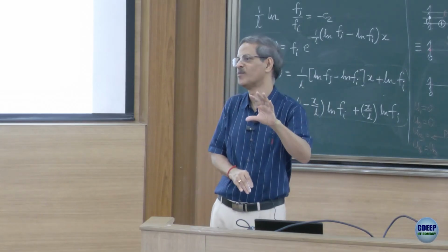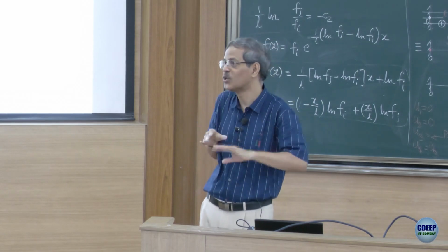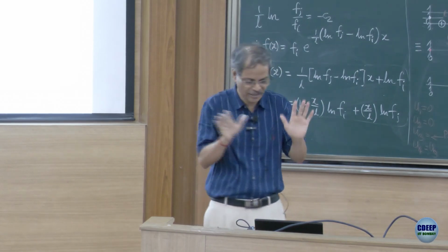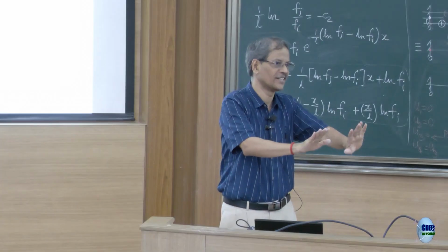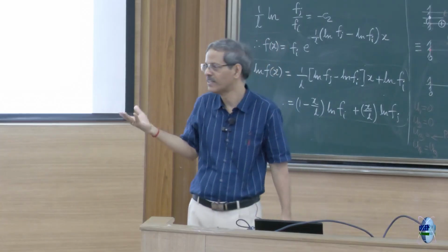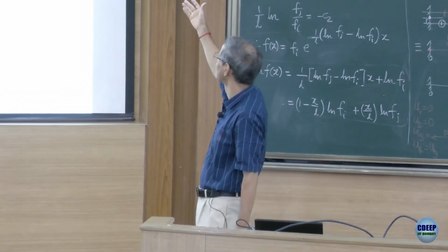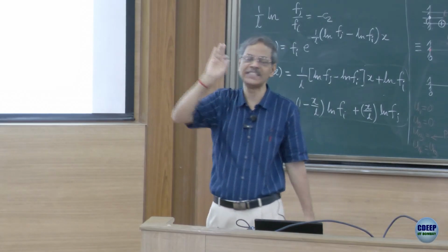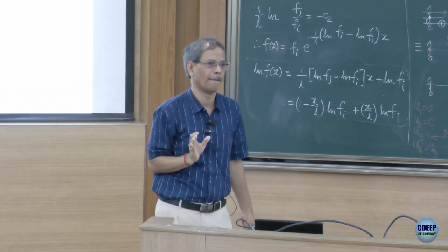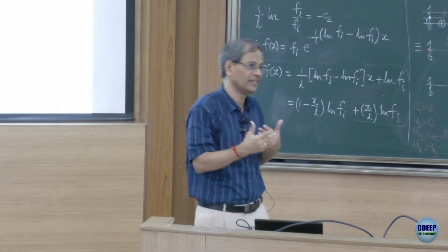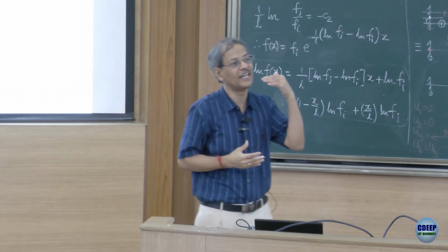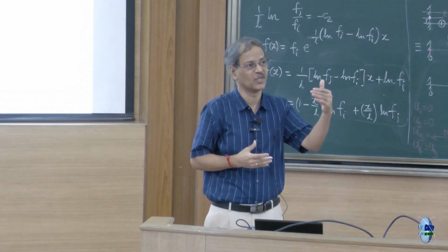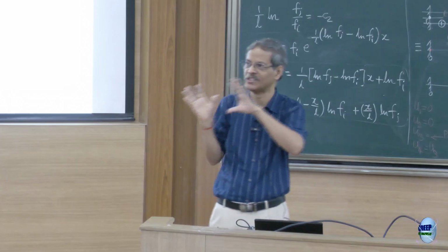This remains behind the computer screen. You won't see this element. It is only in the maths, in the calculations. In the real physical world, that element could still be x1, y1, x2, y2, x3, y3, x4, y4. So, it is a general quadrilateral element. So, what I am proposing is that let there be a coordinate transformation first from xy to zeta eta frame.